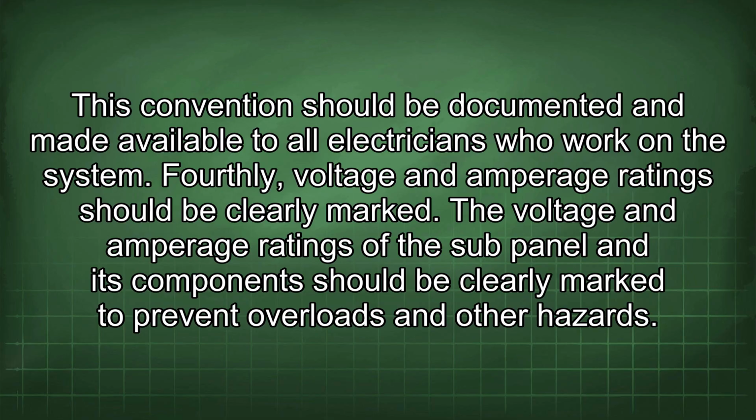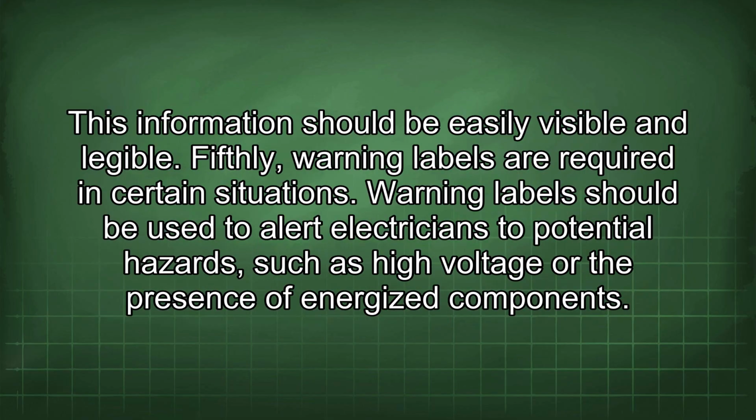Fourthly, voltage and amperage ratings should be clearly marked. The voltage and amperage ratings of the sub-panel and its components should be clearly marked to prevent overloads and other hazards. This information should be easily visible and legible.